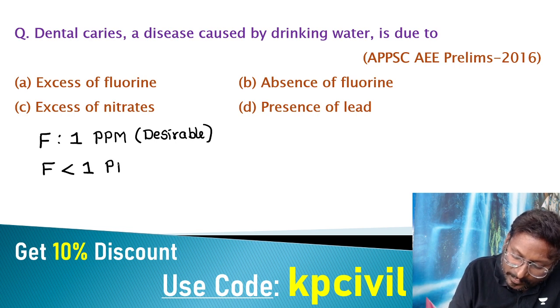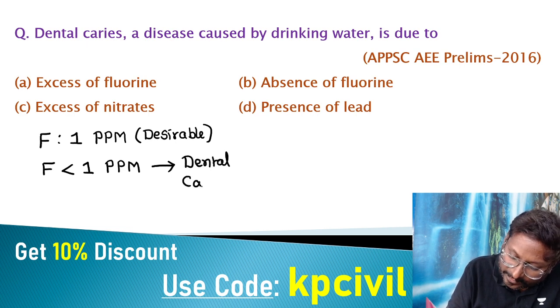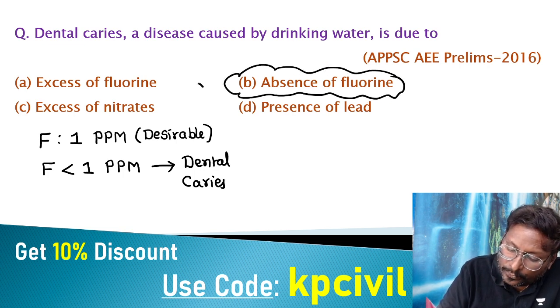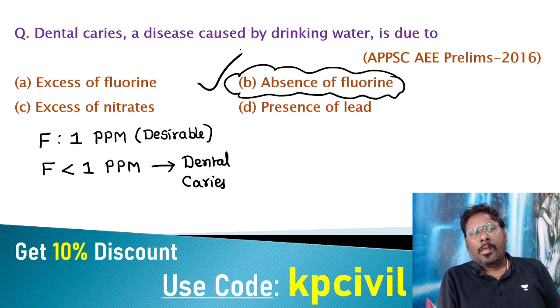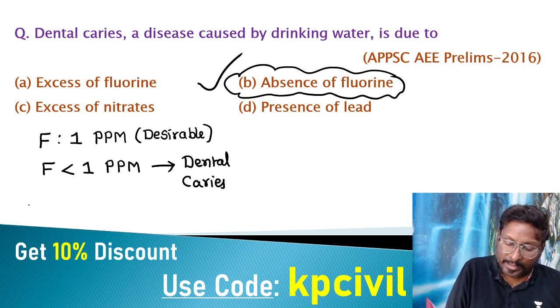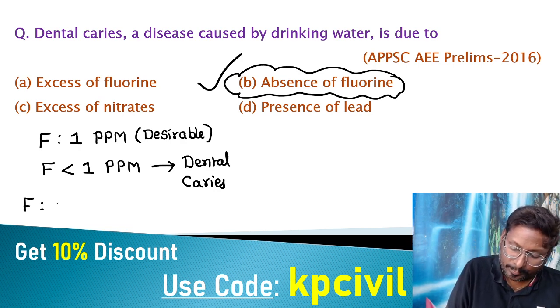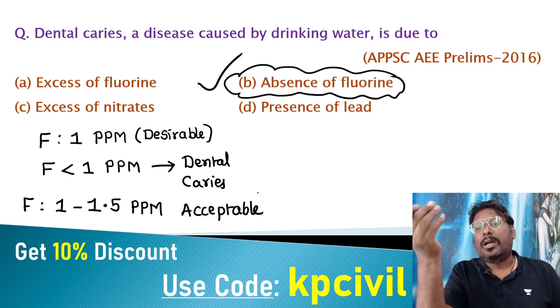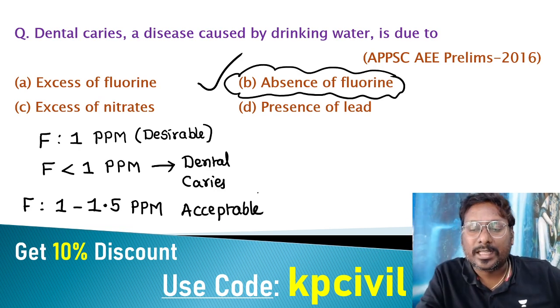Fluoride less than 1 mg/L, a deficit or absence of fluoride, leads to dental caries in children. The maximum permissible limit is 1.5, and 1 to 1.5 is acceptable. Greater than 1.5 is excess, and it will cause fluorosis.